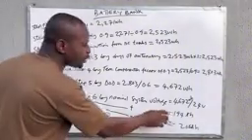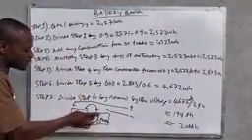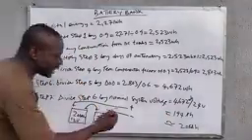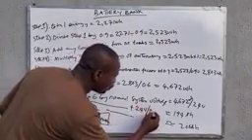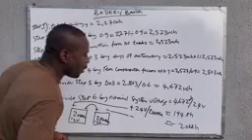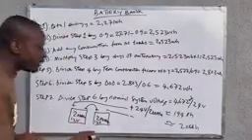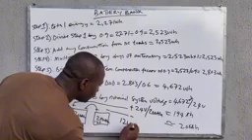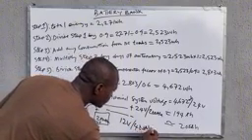It therefore means you are going to use a 12 volt inverter. So if we connect these batteries in parallel, whereas this one now is 24 volts, 200 amp hour, the system will change. It will now be 12 volts and 400 amp hour.